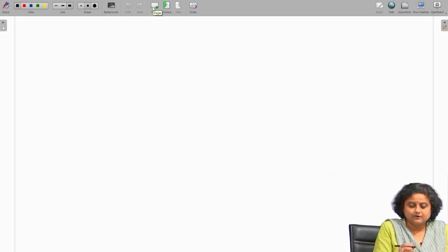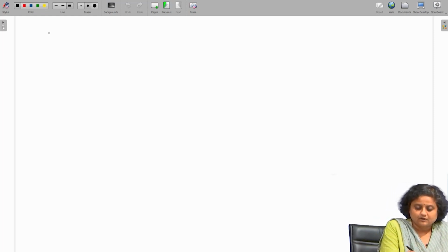So, we have got Vz is equal to B sin n pi Z by L, and we have got that mu is going to be n pi by L. Now, mu square is in turn P by EI.